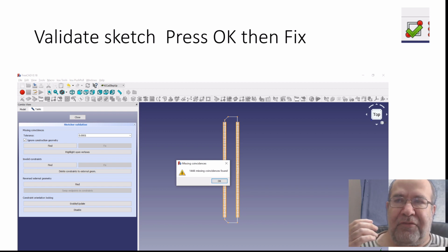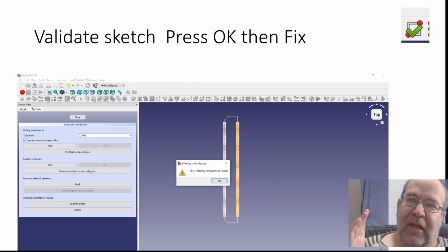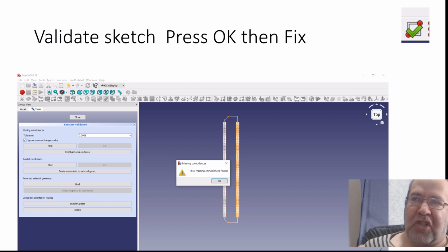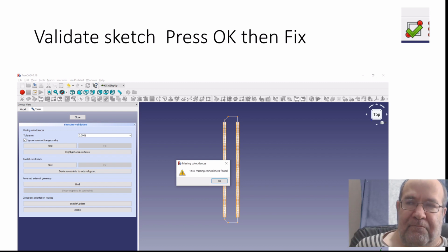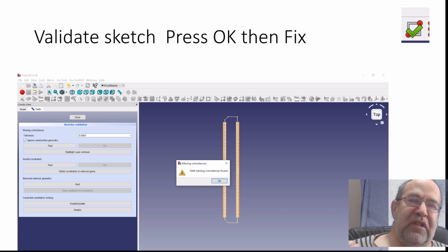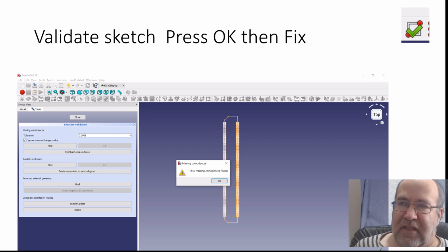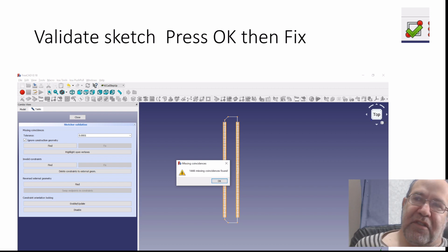For example, if you don't have a full outline of your board shape in Altium, Altium will not be able to know the board shape if you have open holes in your outline. So very often when mechanical engineers export DXF files, they have holes in it; it's not one full continuous line.